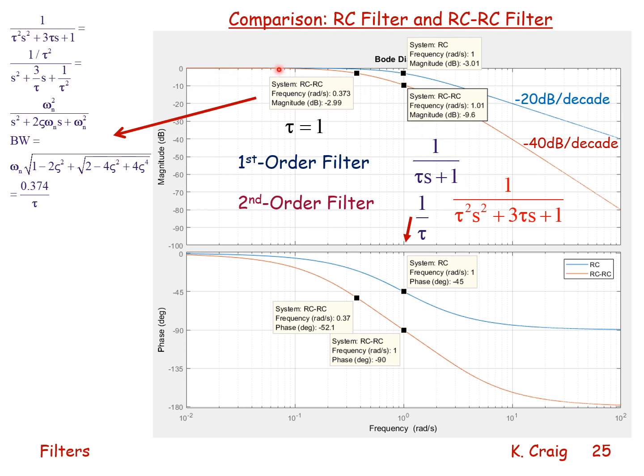It's flat at low frequency at 0 dB, minus 20 dB per decade at high frequency, and the breakpoint, where it's minus 3 dB, is at a frequency of 1 over tau, which is 1, which is 10 to the 0 radians per second. And I noticed that at that frequency, 1 radian per second, the phase angle is minus 45 degrees, as we predict.